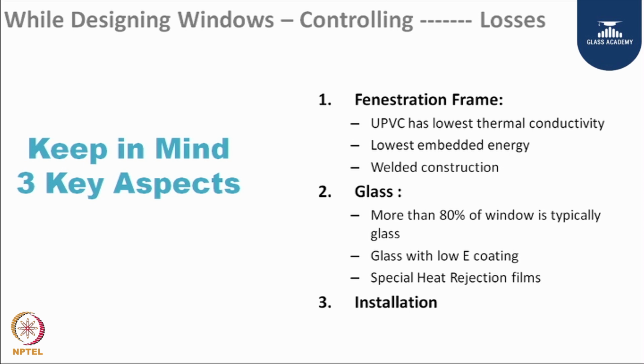Though in most places we do not talk about installation, you might have a very good window design, a good material selected for frame and glass, and it is manufactured in world class factories. But if you do not install it correctly, if you do not seal between the aperture and the window, ultimately whatever you wanted to save leaks through those gaps. So, installation plays a very vital role in controlling any type of losses or enhancing the insulation characteristics.